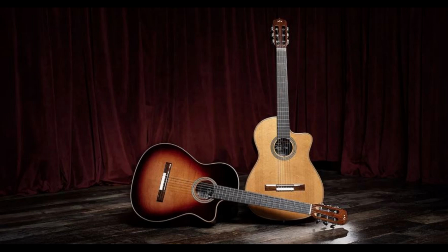The top, back and ribs of an acoustic guitar body are very thin, 1 to 2 millimeters, so a flexible piece of wood called lining is glued into the corners where the rib meets the top and back. This interior reinforcement provides 5 to 20 millimeters of solid gluing area for these corner joints. Solid linings are often used in classical guitars, while curved lining is most often found in steel string acoustics. Curved lining is also called kerfing because it is scored, or incompletely sawn through, to allow it to bend with the shape of the rib.